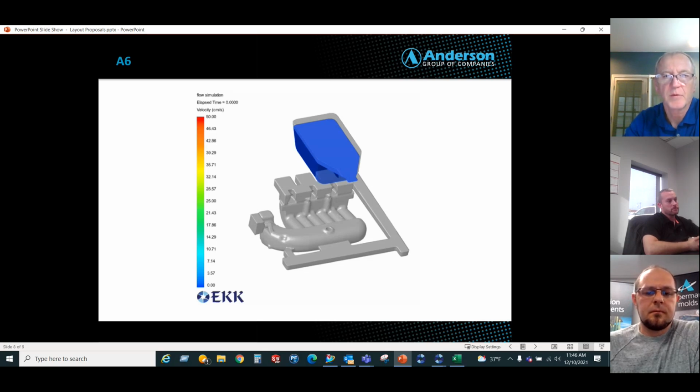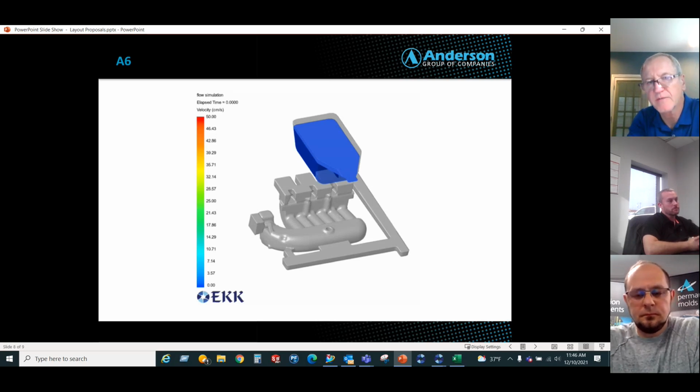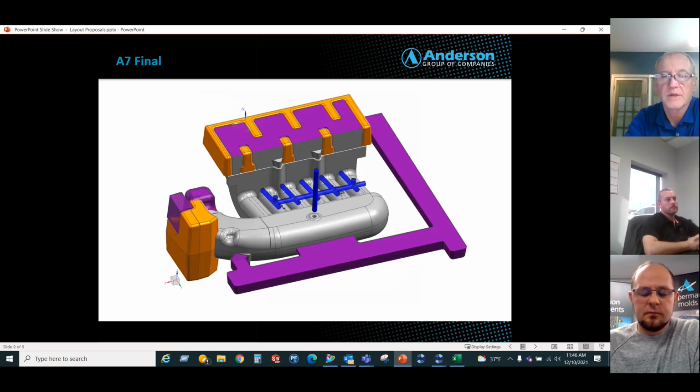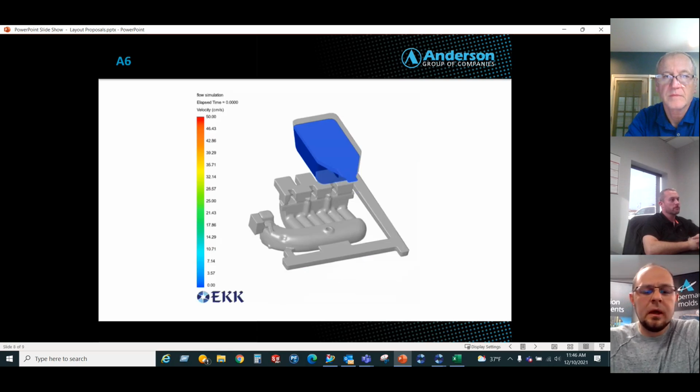Right, and then presumably the size of those gates to get in there are going to be critical. They obviously affect material yield and create bigger issues to remove afterwards, but at the same time you can play with different sizes and get different results. Yes, definitely. That's something that we calculate. We have formulas for gating ratios. There are different standards for different casting processes, but yes, that's something that we calculate for each shot.